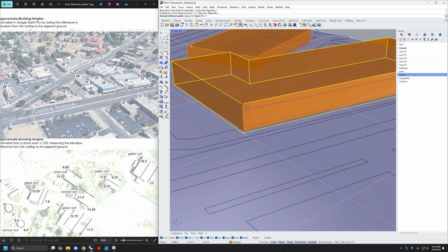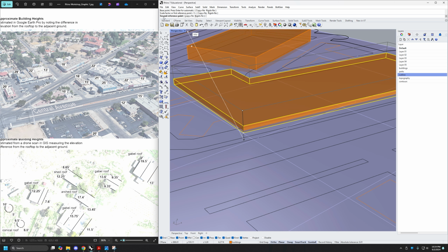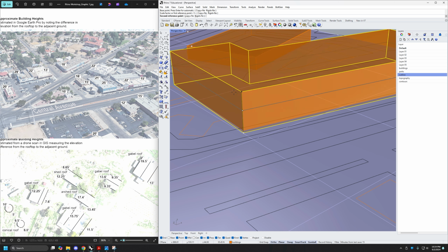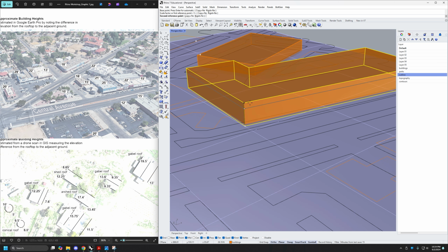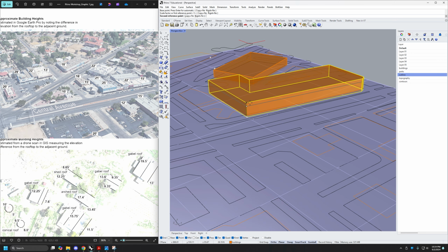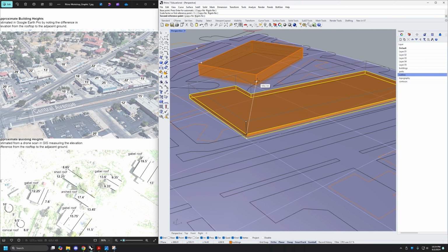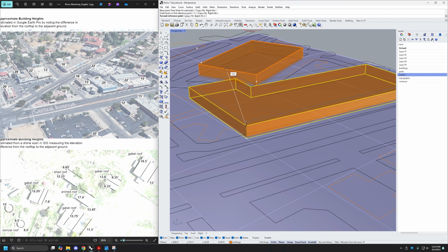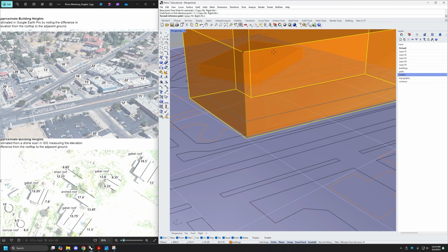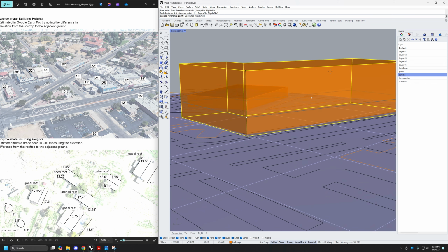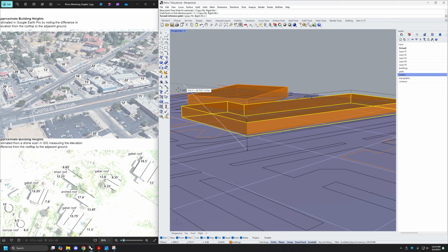And then now we can see by moving our mouse up and down, we can change this vertical scale in one dimension. So this next point of the command is saying second reference point. So we could either, if there was another object that we were referencing and wanted to go snap to that height, or like maybe the midpoint of something else, we could do that. Or what I think is easiest is to enter the dimension that you want these two reference points to be. So we're going to go look at our image.